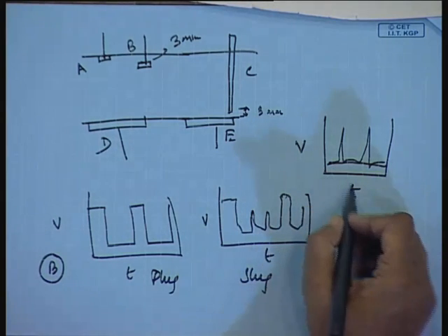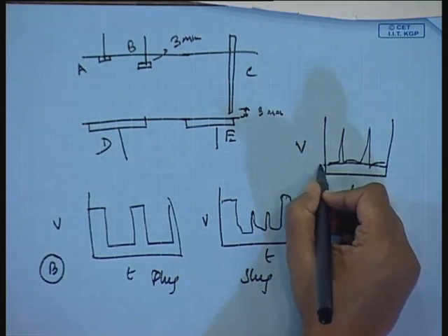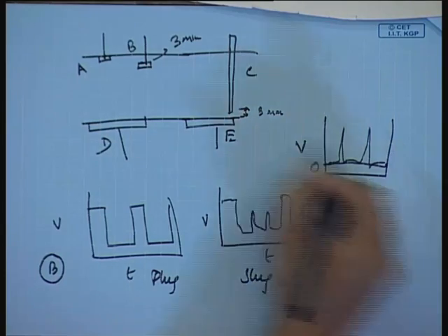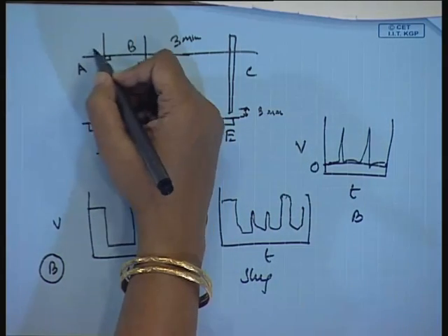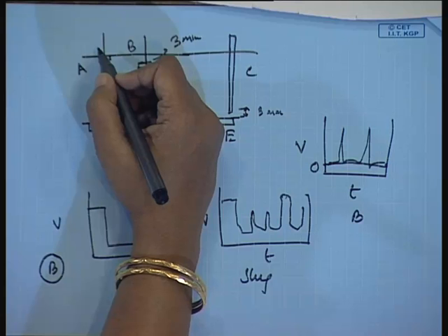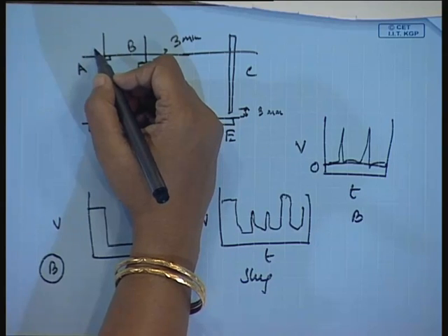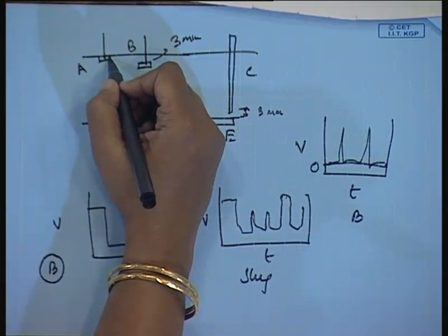So, in annular flow pattern, probe B gives almost a 0 voltage output. Probe A, since there is a thin liquid film, you will not get a 0 voltage output, you will get a positive voltage output. You get my point? Is it clear to all of you? And if the film is wavy, then there will be oscillations in the output of A.